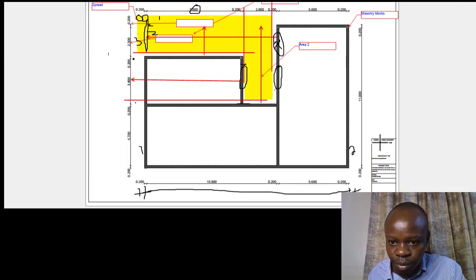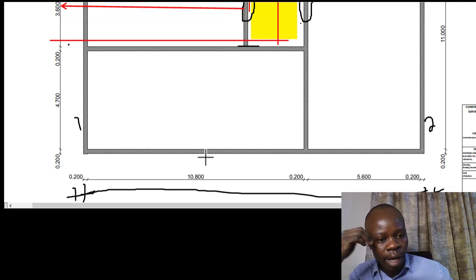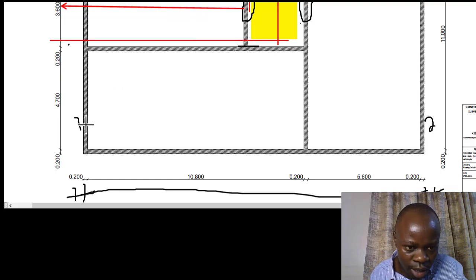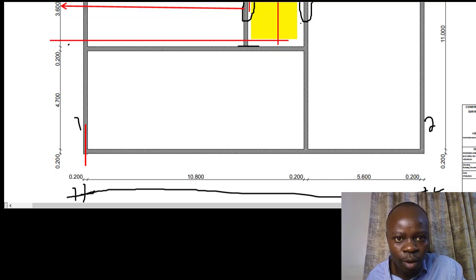The reason why we are taking the 4 corners is this: when you go to this particular plan, you've realized that we got the length taking the full length from one end to the other. But then we don't need it from the external faces. Instead, we need it at the center of the wall, because that is the way I explained previously. We need it at the center, for instance, at that particular part, and also on this other half.